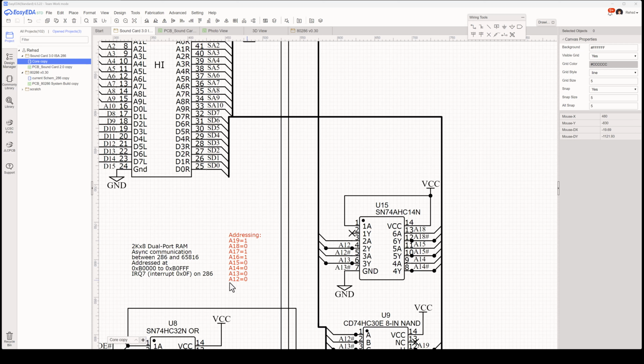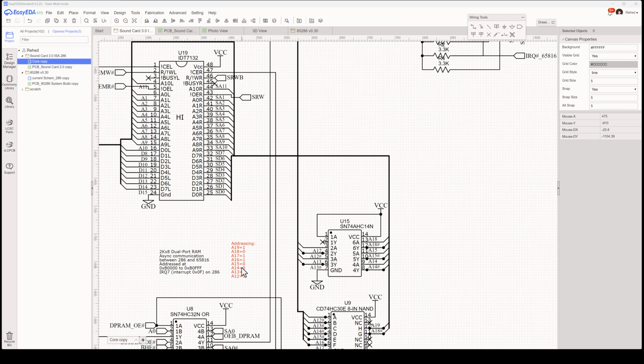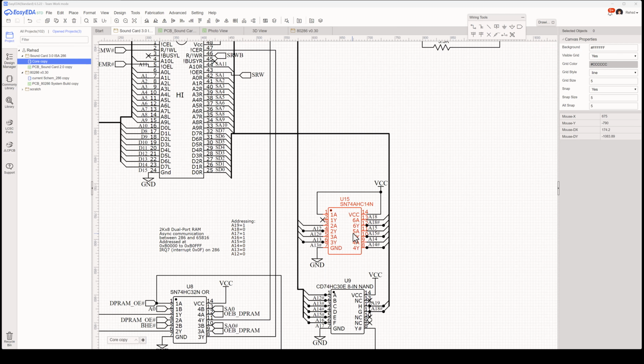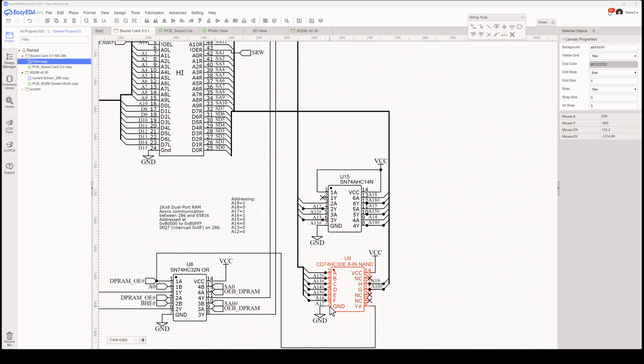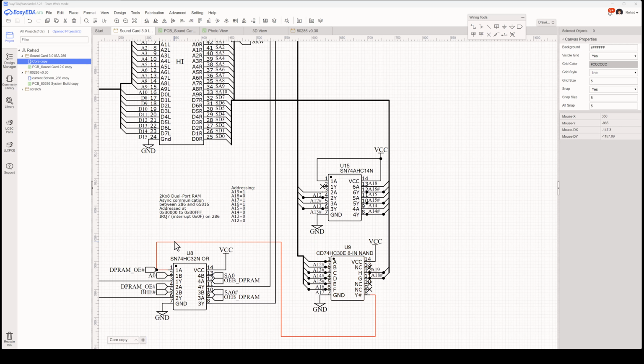If it does match that pattern, then I know I'm in this B0000 to B0FFF range. So I'm bringing in those signals, inverting the ones that are zeros here so that I can get a high, and then running that into an 8-input NAND. There are 8 of those, and that works perfectly to run through the 8-input NAND. And out of that, I have a signal that tells me I'm in the right address space.